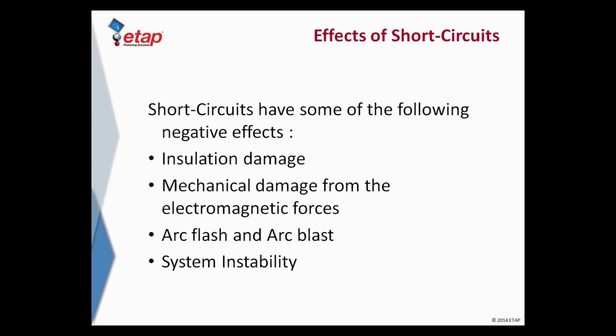So the short circuits have negative effects to your system and to your equipment. You can have insulation damage, mechanical damage from the electromagnetic forces. You could also have arc flash and arc blast events. And some faults can also lead to system instability.